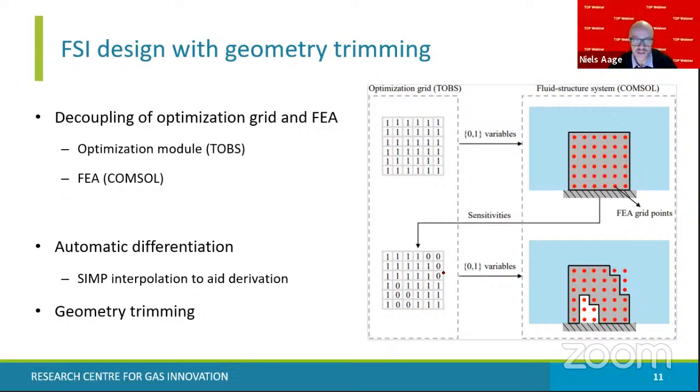Yes, sorry, it was along the same line. So I guess this works very well due to a one-way coupling. Speaking of the sensitivities, if it was a two-way coupled problem, speaking again of large deformations, would this segregated analysis still be possible? Or how would you think about transferring information between the two different solver packages?